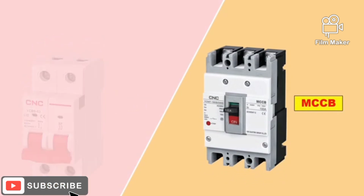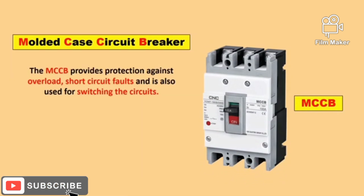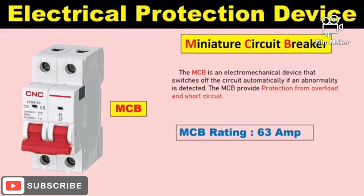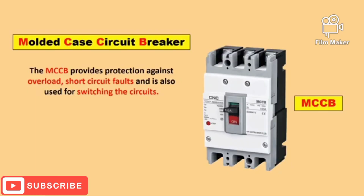After this, next device is MCCB. Full form of MCCB is molded case circuit breaker. Friends, the MCB you have, or if you are going to buy a MCB, then a maximum of 63 ampere rating MCB you can buy. These days you can find a 100 ampere rating MCB also, but before, till 63 ampere rating MCB were available in the market. Now if you want a protection device of even higher rating, then in this condition you have to buy a MCCB. MCCB also provides protection from overload and short circuit.